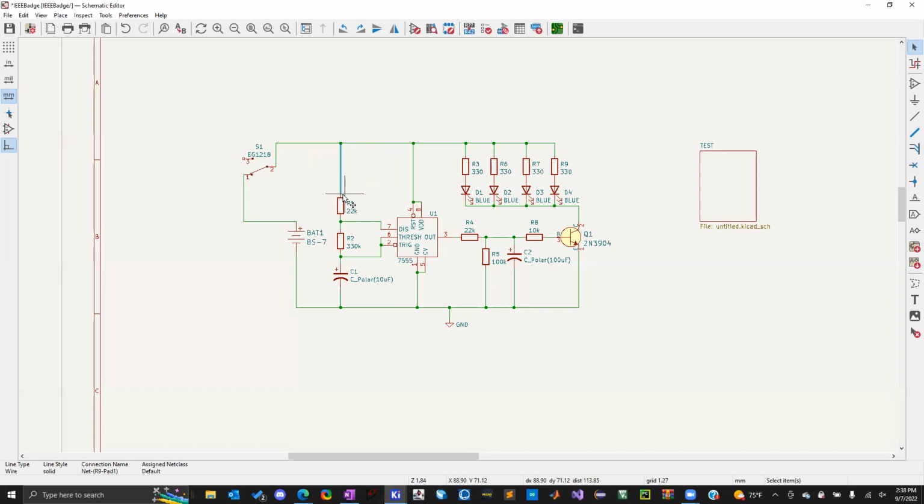Another thing, usually if you have a lot of extra space, you want to create a pour of copper or a plane of copper. That's when you have an entire side of the PCB as copper, or a huge block or section of PCB is copper. Usually it's best practice to take the extra space and make it part of the ground connection, because it increases your signal integrity for your signal pins. We won't have to worry about any of that in this case, but if you ever get really serious in PCB design, that's something you'll have to consider.